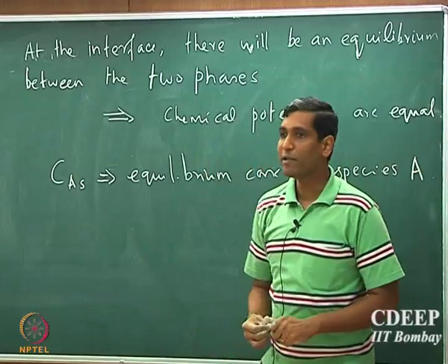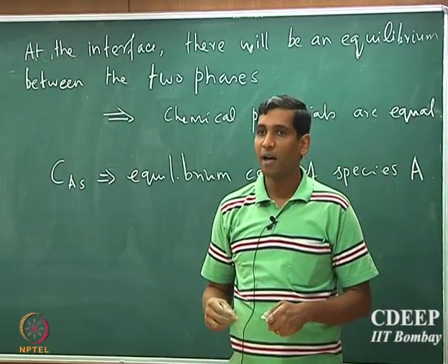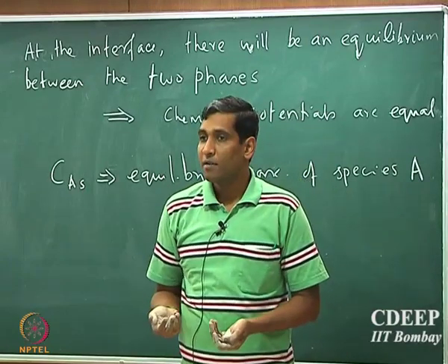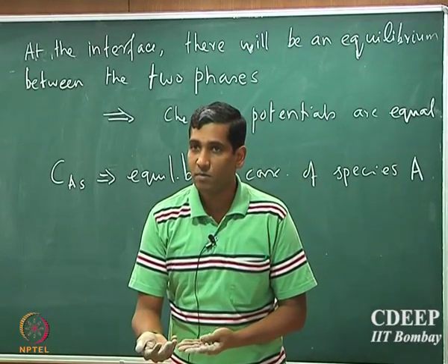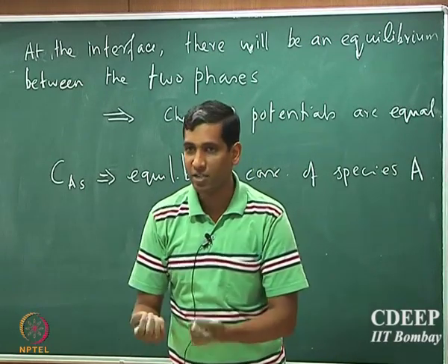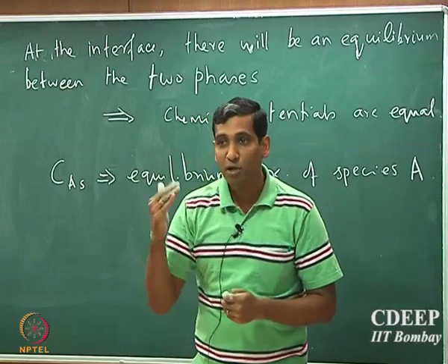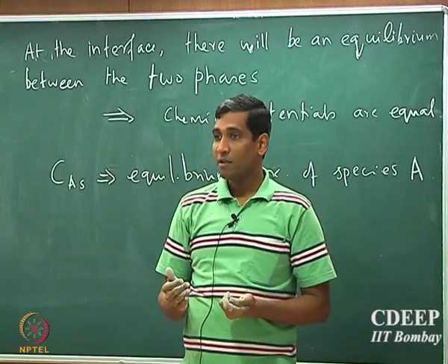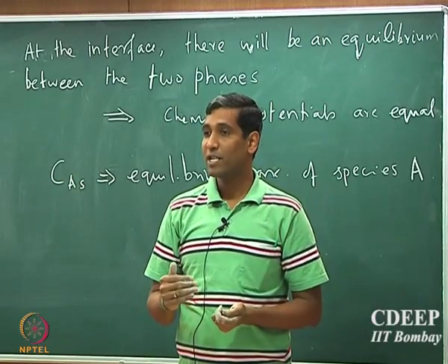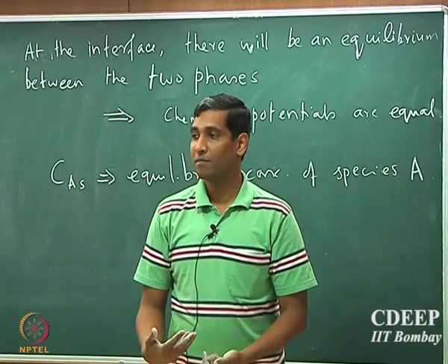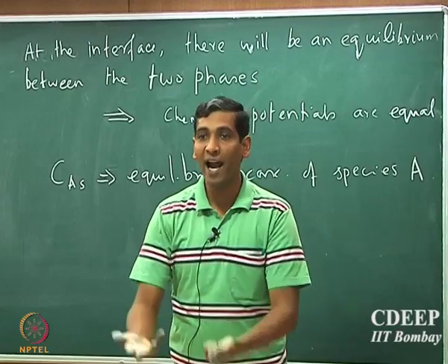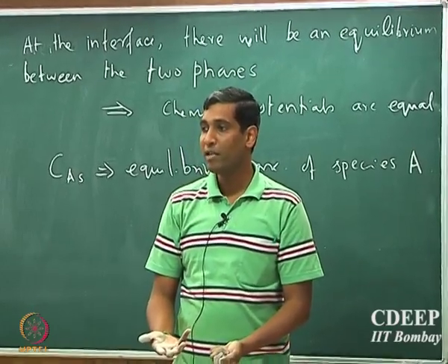Now what it means is that unlike in the case of heat transport, where you supply heat, the material is going to have a certain capacity, so it's going to take energy and the temperature is going to increase. That's not the case with mass transport. So you always have the issue of what is called saturation. There is only a certain amount of solubility of a particular species in a given medium, right? You cannot add more species to it if you are above the solubility limit.